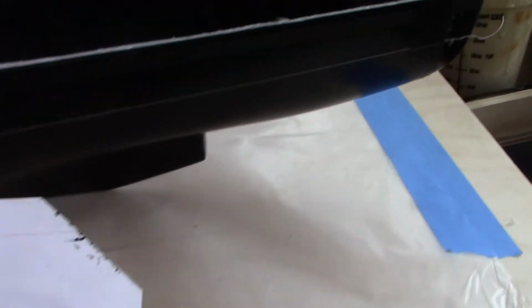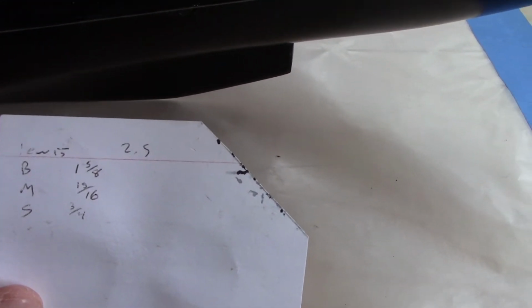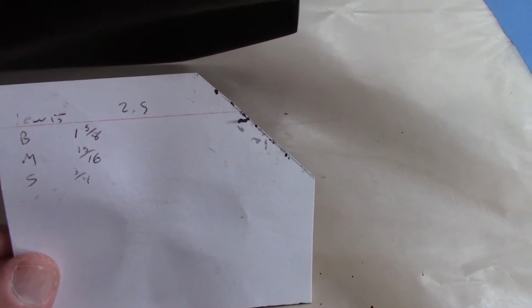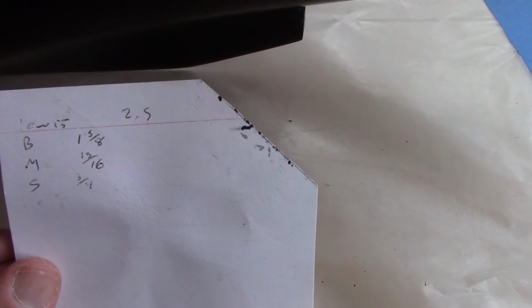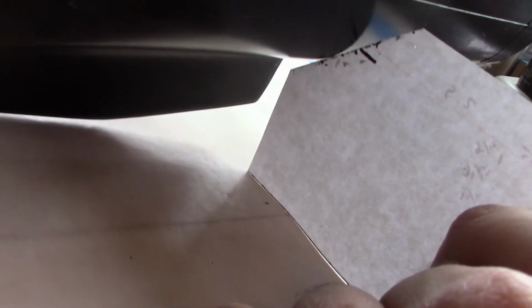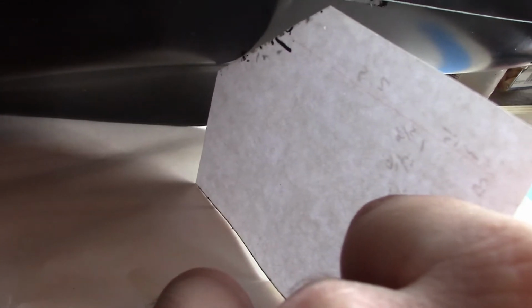So how do you figure out the 45 degree? I showed this before, but what I do is I cut a very basic 45-degree angle. I snip the end off, but to make that you just measure the same distance from one corner down two edges and then cut. Then you just hold it up against the hull there, and just put a mark right where it touches there. And then you just do this every few inches down the hull. And you can see the point pretty clearly there.